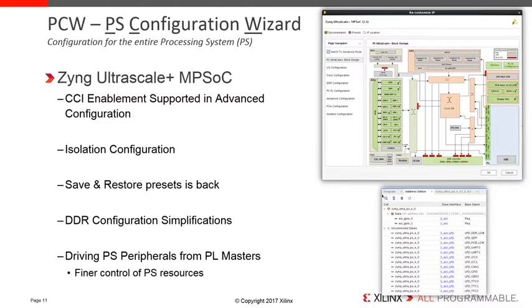The Processor Configuration Wizard now supports Zynq UltraScale+ MPSoC. The features include cache-coherent interface support, isolation configuration, save and restore presets, DDR configuration simplifications, and finer control of processor subsystem resources. Isolation configuration is the ability to define and isolate subsystems within the PS using Zynq UltraScale+ MPSoC's XMPU, or Xilinx Memory Protection Unit, and XPPU, or Xilinx Peripheral Protection Unit.